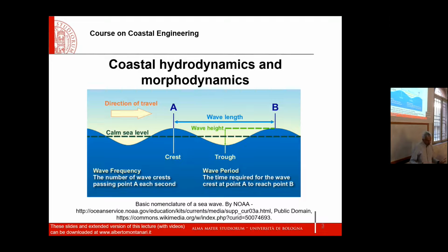And the waves tend to displace this loose material, which means erosion, deposition. Deposition is also called accretion. So the effect of waves is not only erosion. We mention erosion very frequently because we are concerned by erosion. We are not usually concerned by accretion, because accretion means that the beach becomes more protected, becomes larger. But actually, these two phenomena occur together. If the sea erodes on one side, then there is accretion on other sides.